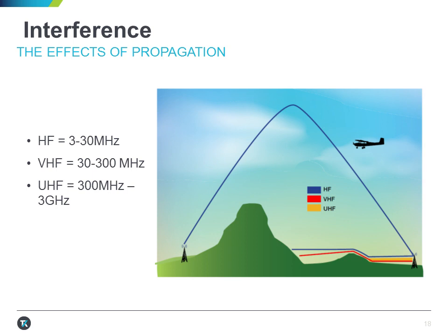When considering the source of interference, we have to consider what frequency range we're operating in. In general, if we think of HF, VHF, and UHF spectrum, we have different propagation characteristics for each frequency range. By physics, the HF, or 3 to 30 megahertz frequency range, can have sources of interference propagate from much further distances compared to VHF or UHF communications.